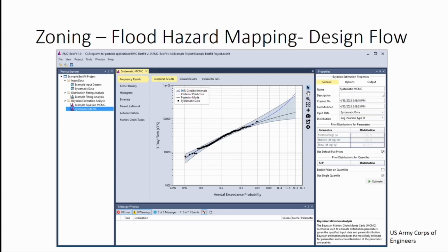So to do this, in terms of the hydrology, we need that design flow. The design flow will be a flood that is selected by the municipality or a jurisdiction as to what they are comfortable in handling. Of course, we can't handle every flood, but we have to be comfortable enough to say that, based on the economies of the society, we are comfortable with this level of flood. So that becomes our design flood or regulatory flood.